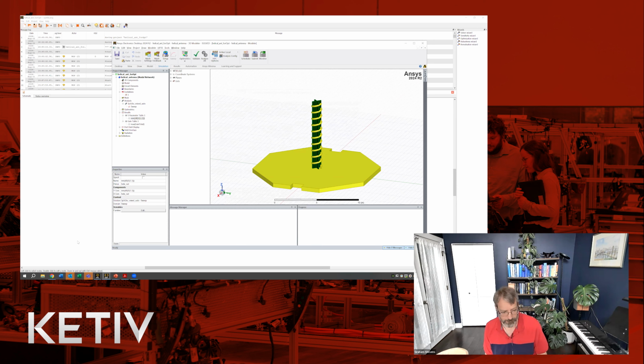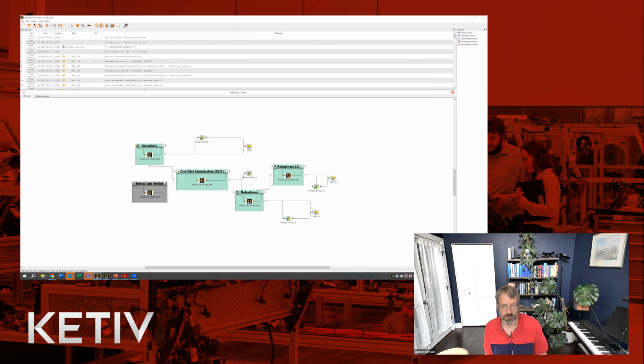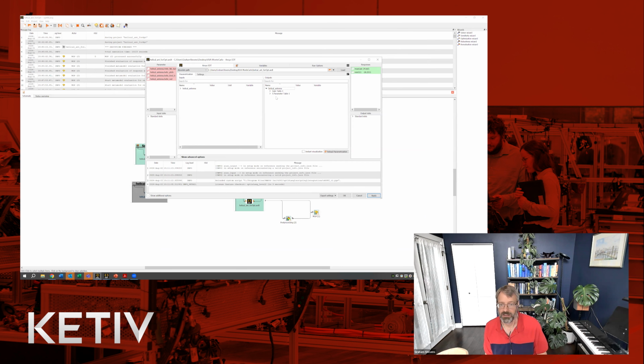Once all that's done, you then hop back to Optislang, and as I said, go through the solver wizard and initially set this up. What will happen is you'll come in and you'll see these variables here. Typically, you'll right-click on them and use as internal variable to define those outputs and say, yes, this is what I want to use.